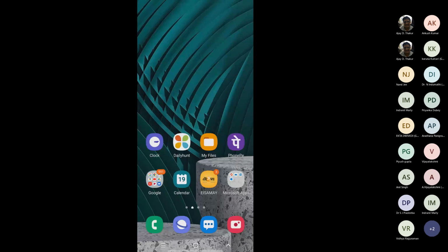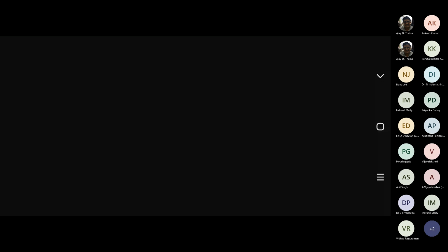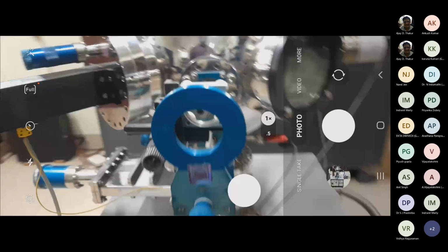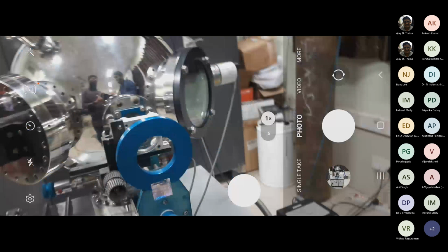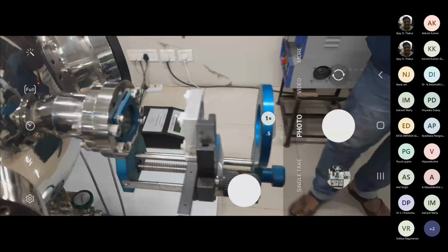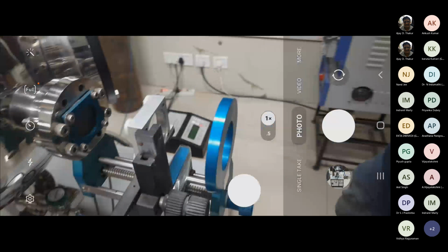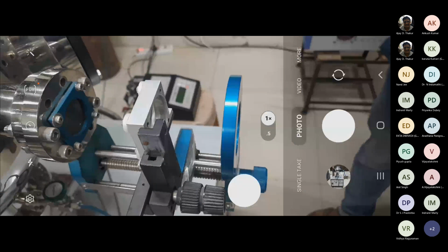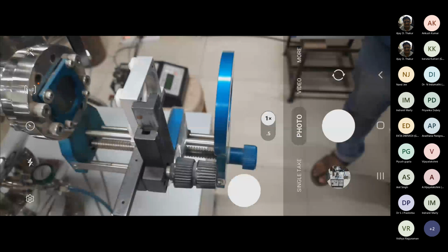Indranil made a very important point. So Indranil, can you focus on the lens part? Sir, we talked about the spot size, right? So you can see that right before entering the chamber, there is a lens assembly. This is based on HR optics, basically of a material which can tolerate such high energy laser beams without degrading or developing color centers. And this is a converging lens. So what it really does is it helps in reducing the spot size.